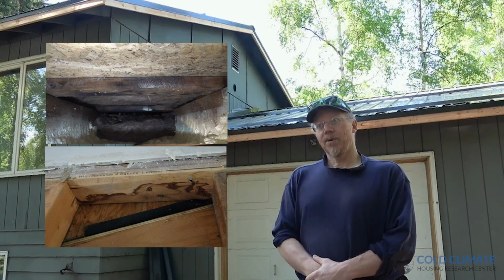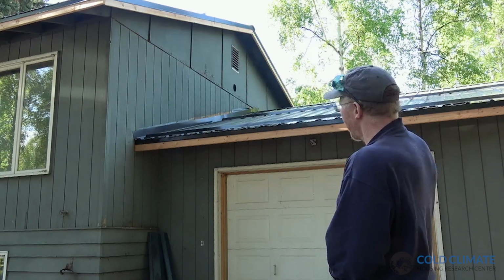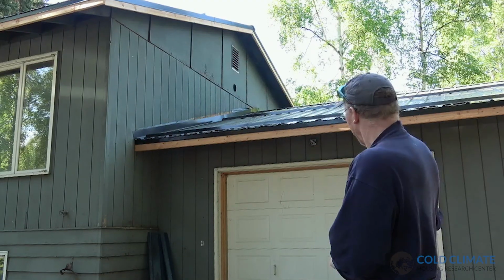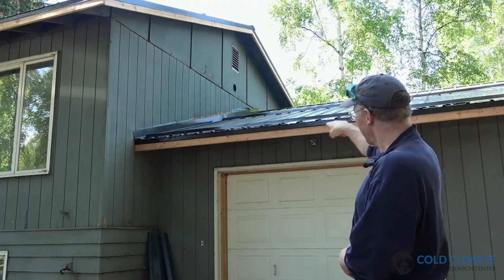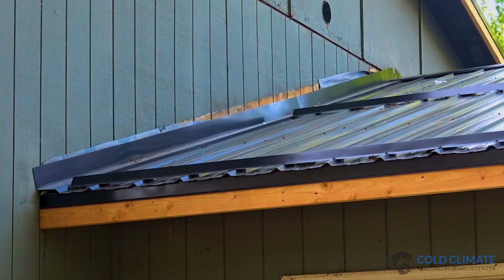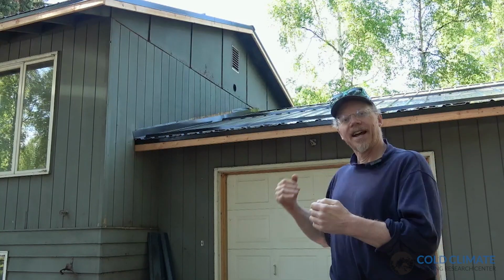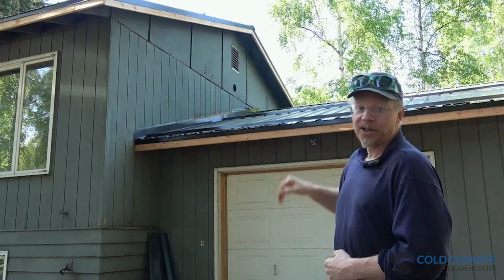Now, what we've got here in particular is a 1970s home, and you can see the garage is attached to the house, and it's a split level. And the problem area is where the garage roof intersects the house wall. This isn't exactly how this problem occurs in every situation. It's really anytime you have one heated structure attached to another and how you transition your insulation and your air barrier through that wall assembly.